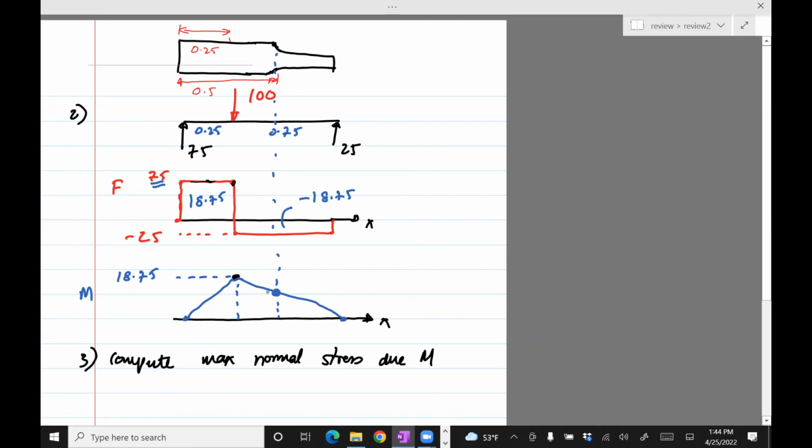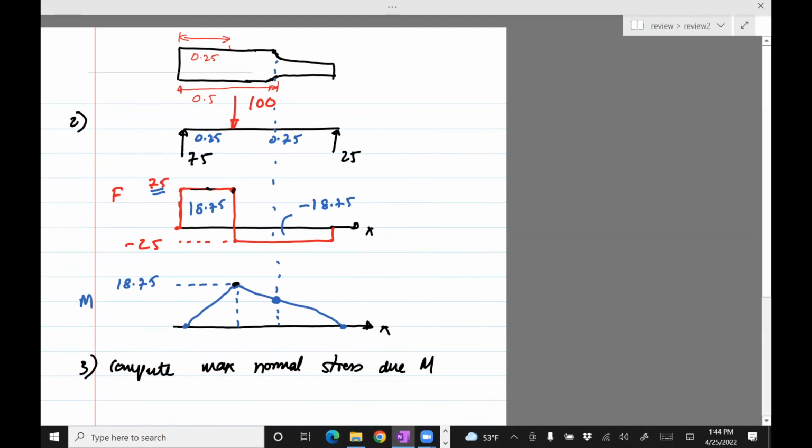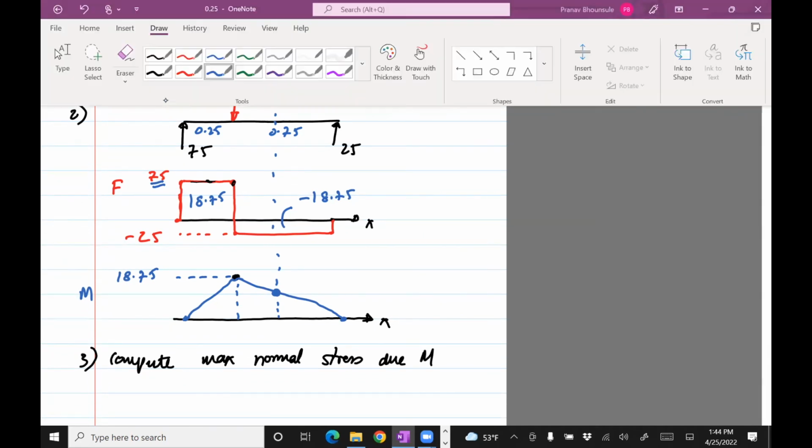But they give you that formula and it's force over area, right? No, it's not force over area. There's no axial stress. This is a beam problem. Oh, you have to find the moment. No, you have to find the moment. You cannot escape that. If you're given the axial force, you don't have to find the moment, but there is no axial loading in this case. This problem has bending loads. You can see this diagram. Look at this diagram.